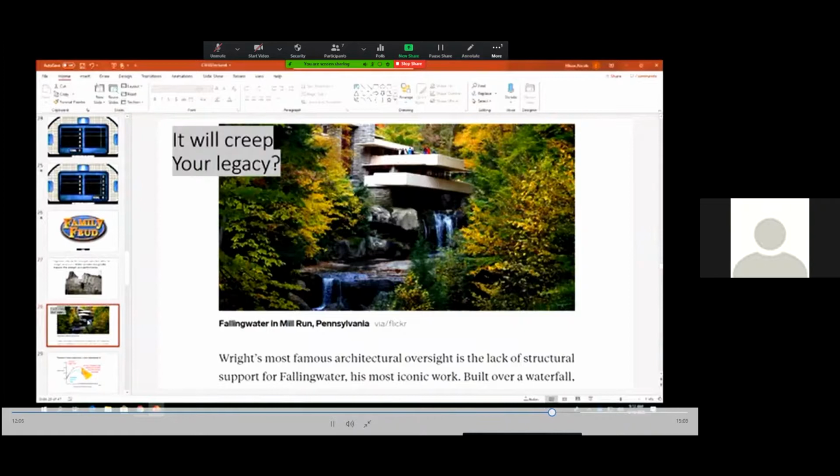I actually had a project in Durango. There's a college there. And they had this slab that was out there deflecting. And they're like, it's so uneven, you can feel it. Let's put some more concrete on it to level it out. It's a cantilever. What happened? It deflected more. So then they said, maybe we should hire an engineer and have them look at it instead of just throwing some more load on it. So we have to take that into account when we do our designs, that it's going to creep. And you don't want to have one of your structures fail. That's the last call you want.